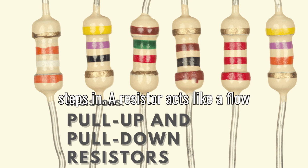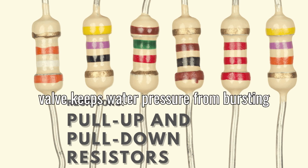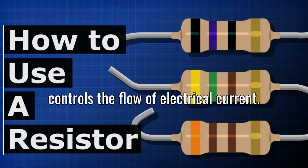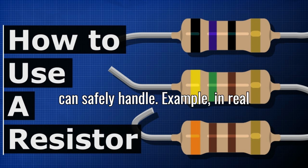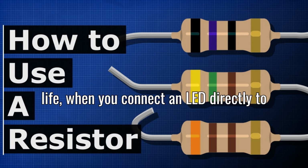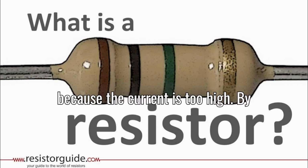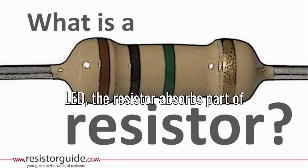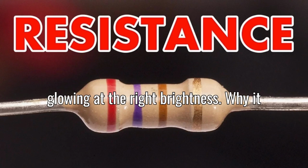A resistor acts like a flow restrictor in a water pipe. Just as a valve keeps water pressure from bursting your pipes, a resistor reduces and controls the flow of electrical current so that components only receive what they can safely handle. Example in real life. When you connect an LED directly to a battery, it will likely burn out because the current is too high. By placing a resistor in series with the LED, the resistor absorbs part of that current, keeping the LED safe and glowing at the right brightness.